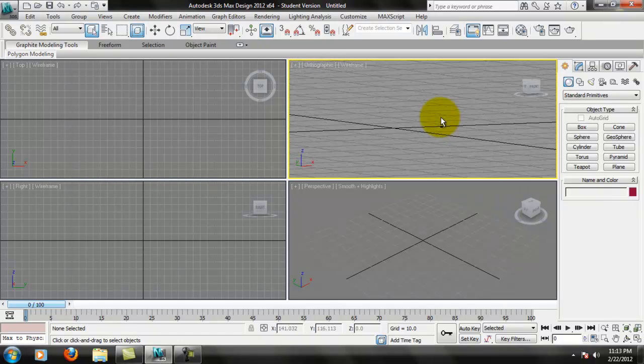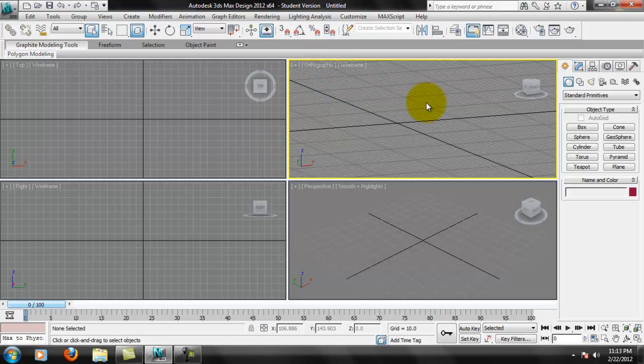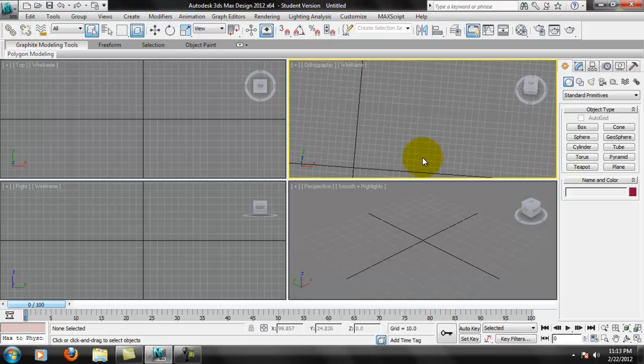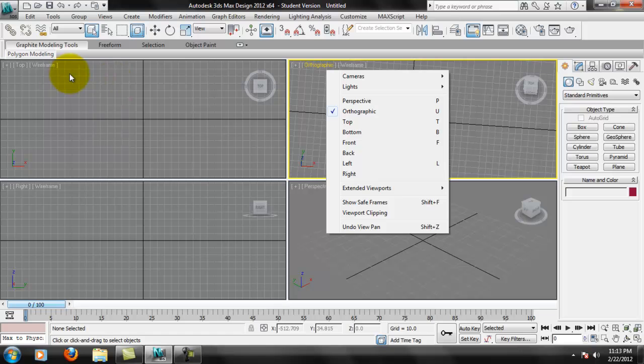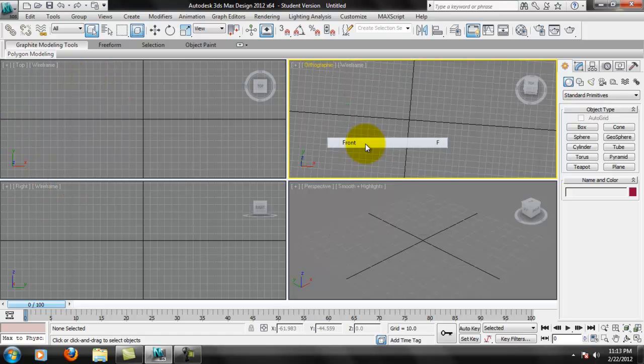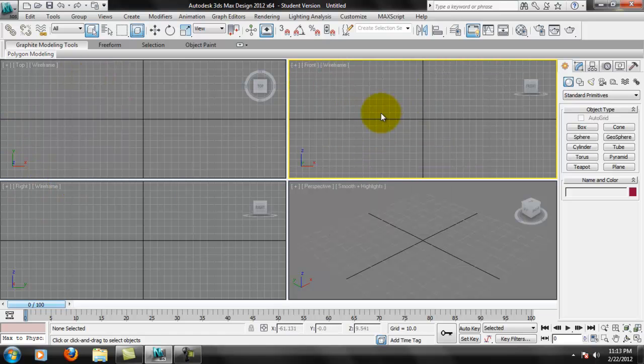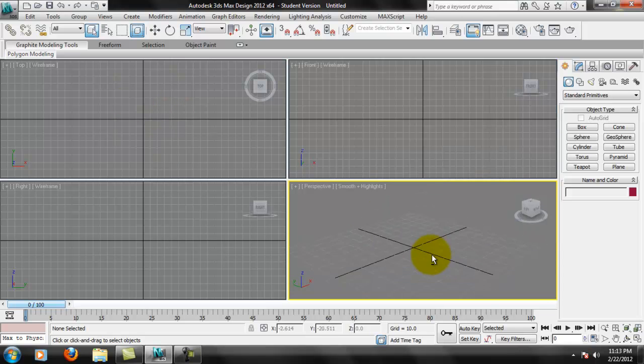And you can see the second that I orbit, I've changed this view type to orthographic. Sometimes students will get confused because they'll have something that looks like it's the top view, but you're not exactly at the top view. So you need to pay attention as you're working to what this view actually says, and you can usually tell by the grid. You usually leave the perspective to look around in three-dimensional space.